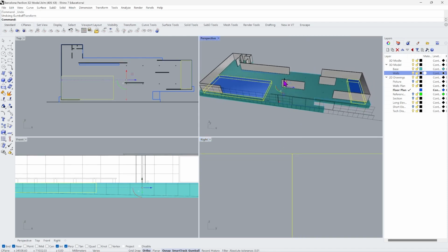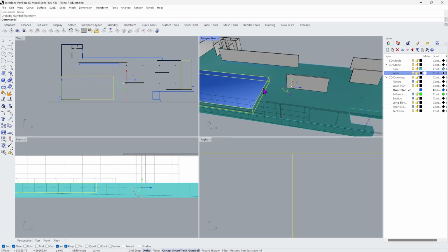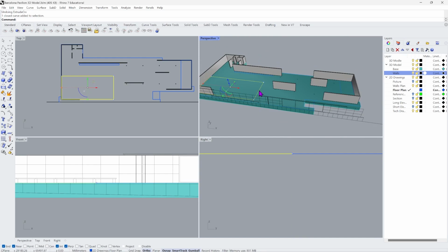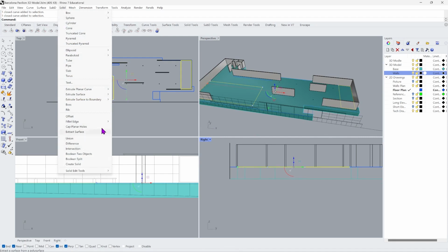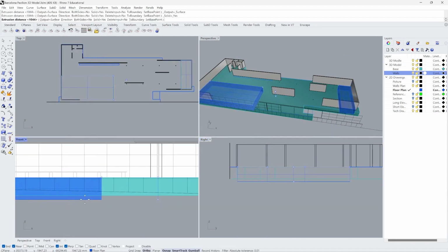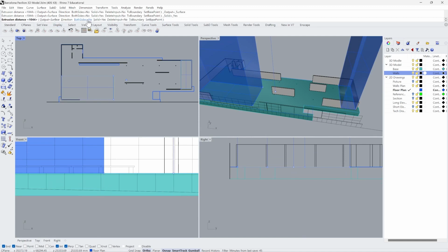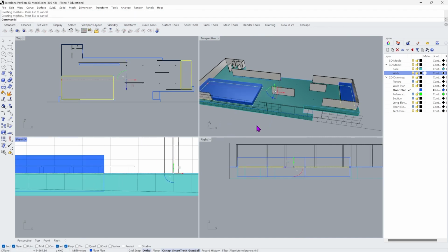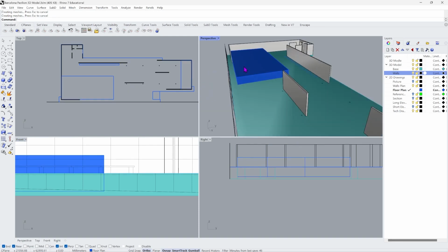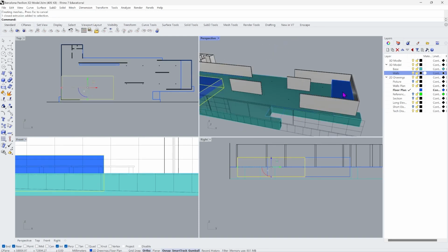Or another option as well, to make sure that your subtract tool will work fine. When you're creating your 2 rectangles that you're going to be using to cut out your pools with, when you go to solid and you're going to extrude those curves down, in the brackets you have option for both sides. Click yes, and you can see that now you create an extrusion both directions. And because we're only going to be using those boxes to cut a swimming pool out of a base, it doesn't really matter if they go in both directions or no. We're not going to be keeping those rectangles.